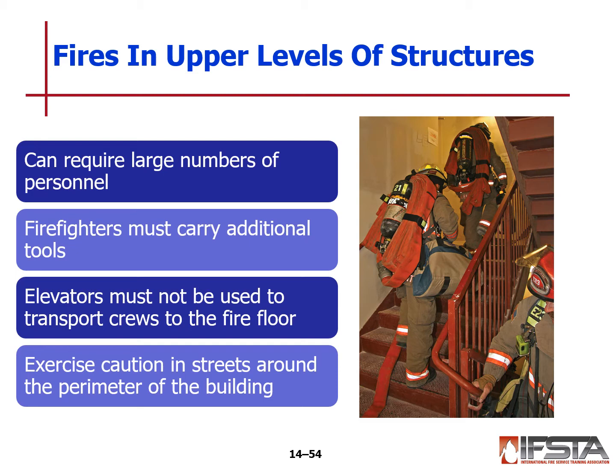And there may be situations where all of the elevators have recalled because of smoke in the hoistways, and that means that we're not going to be able to use them at all. Exercise caution in streets around the perimeter of the building as well.